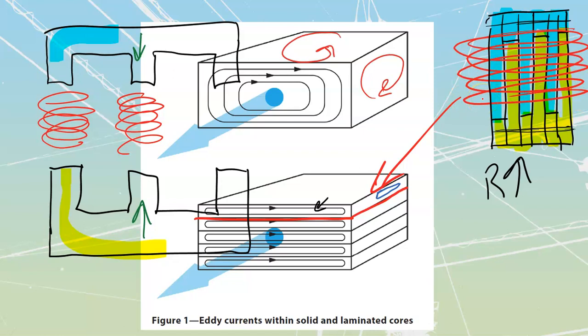For low power, low voltage transformers, usually it's going to be a relatively thin amount of insulation that we place around the windings. It's going to be varnish or enamel, which is basically an oil-based type of paint that goes on there. Now, varnishes and enamels can, over time, degas, where they lose their VOCs, or volatile organic compounds, which are the things that make oily things oily, for lack of a better, more sciencey term.